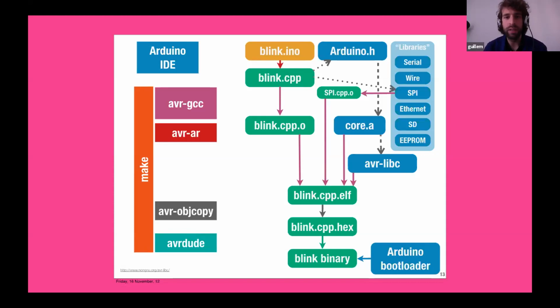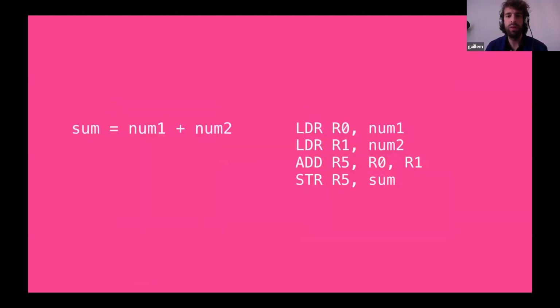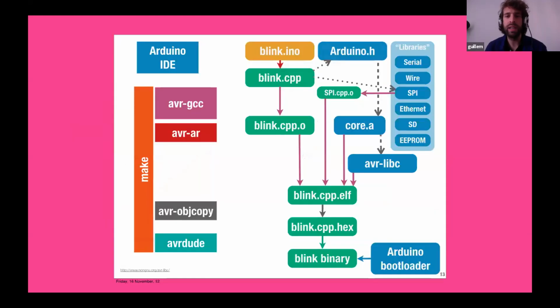And this is important because it means that once the Arduino header is inside your blink.ino file and your file is renamed blink.cpp, even though it changed almost nothing, just having all this Arduino information, all this Arduino library inside, all this pre-made code, it allows the code to be ready to compile. And compile basically means transforming all these instructions that you type in the C language or in the Arduino language into something that looks a little bit more like what you see here on your right. It means transforming them into instructions that your processor could execute.